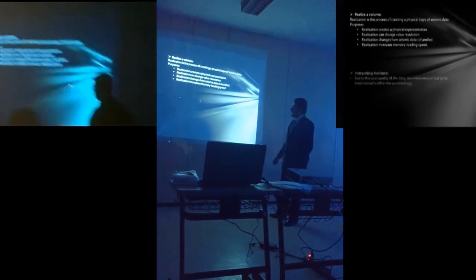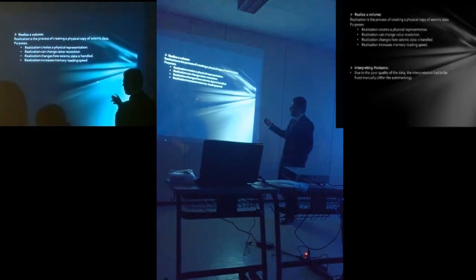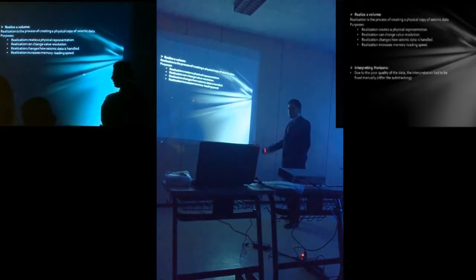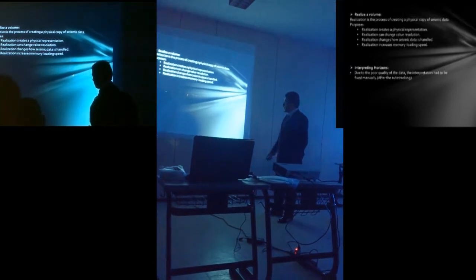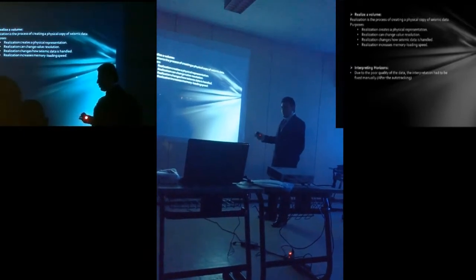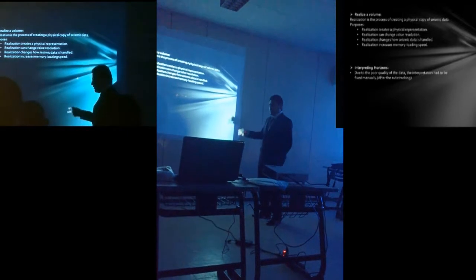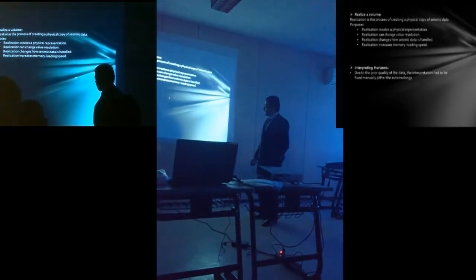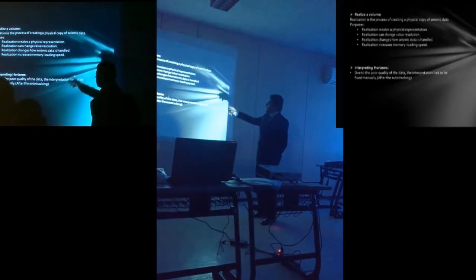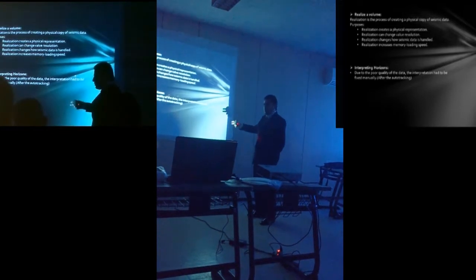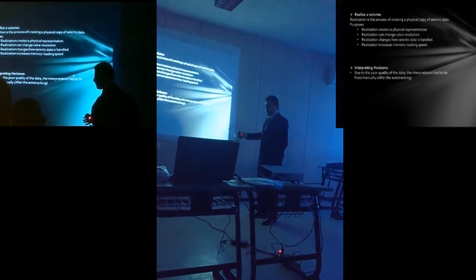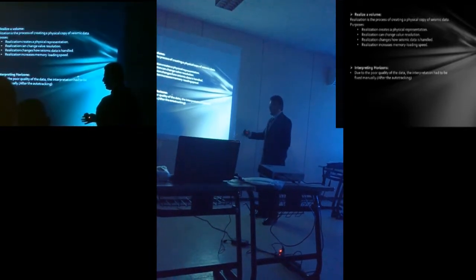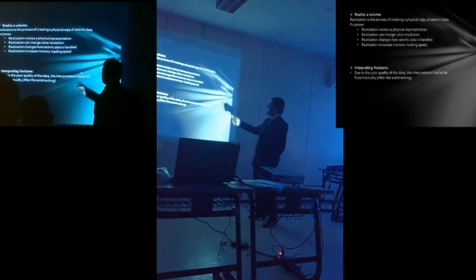Second is realizing the volume. This step is important because it can save a lot of time. Realizing helps to create a physical representation, which will save the seismic cube in the project. You don't need to load it each time you start the project. And you can reduce the resolution. It will lower the resolution and the size, so you can move and make the interpretation through each inline and crossline faster.